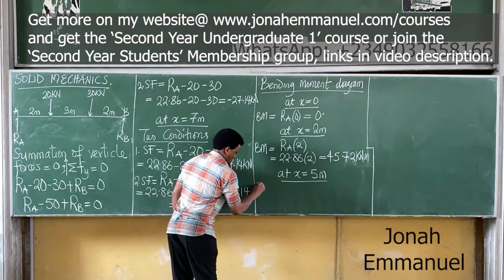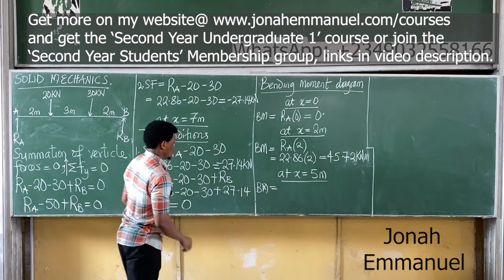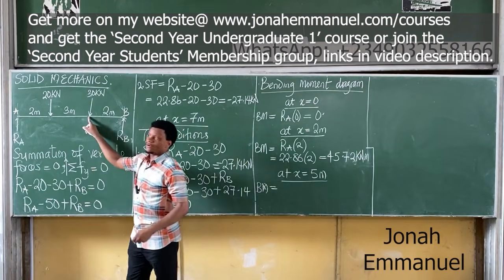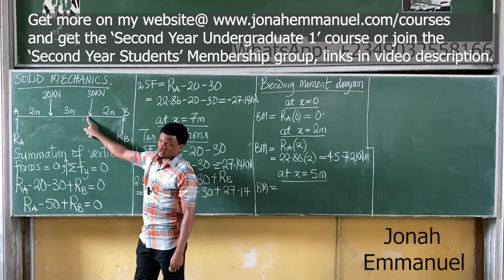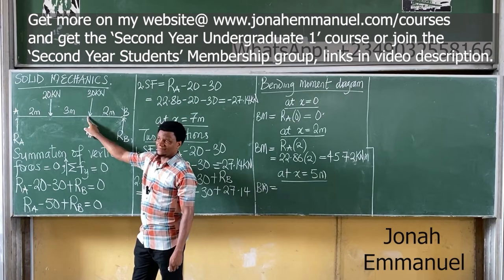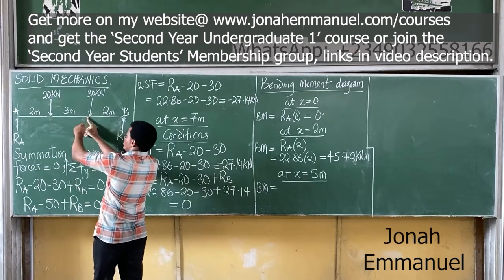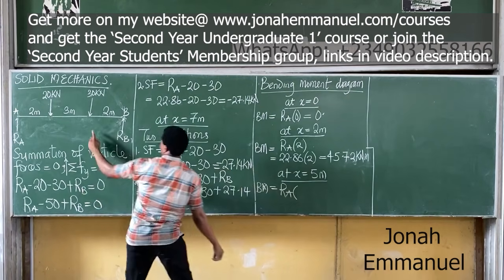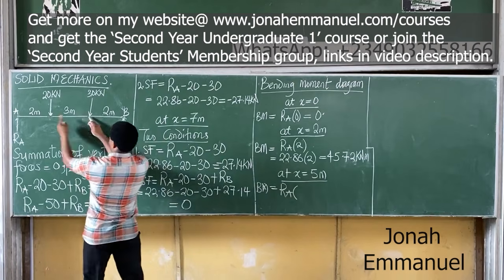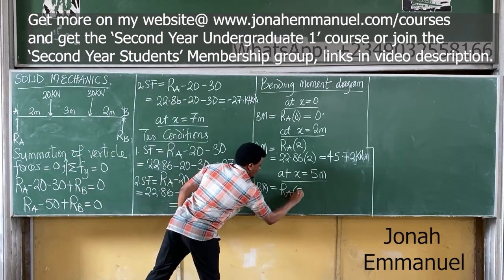At x equal to 5 meters, what's the bending moment? Bending moment is equal to, look up please, at 5 meters, here's where we are. Here. Please, before this point, how many forces do you have? 2. So please, what's the first one there? RA is going this way, clockwise or anti-clockwise? So it becomes RA. For RA, what's your distance? Check. What's the distance from RA? 2 plus 3, that's 5.